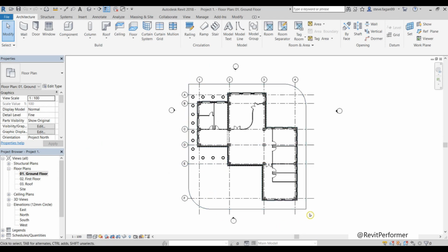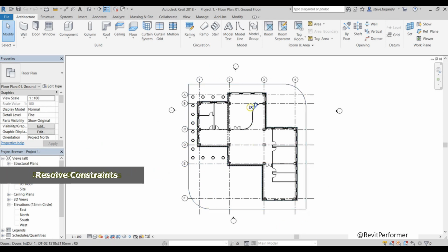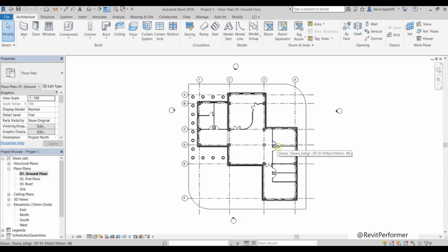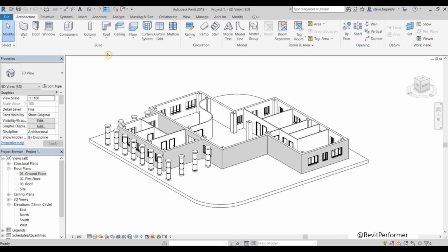We've created the outer footpath boundary, the ground floor slab, external walls, the windows, and internal doors, as well as our internal partitions. The next stage of the project, we're going to build up and create the first floor. To get a better view of what we're going to be doing, I'm going to open up my 3D view. So up the top here, the quick access panel, selecting the 3D house to open up my 3D view.